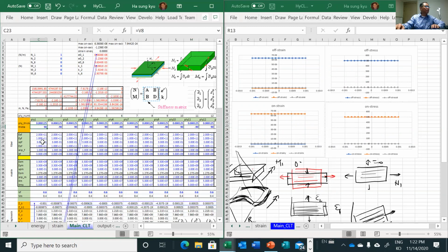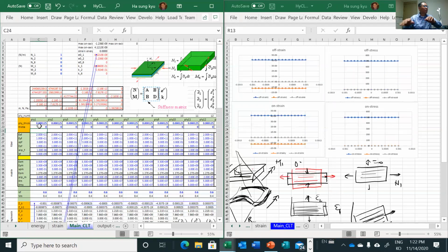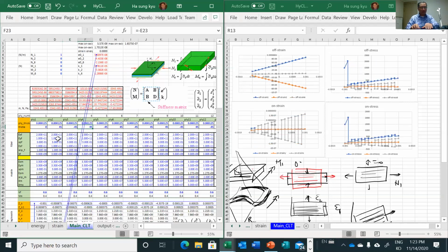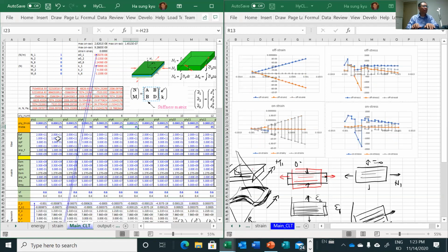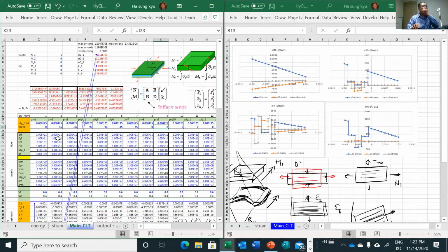Currently, the layup sequence is all 0. I would like to start with all 0, for the given uniaxial load, right? And then you can play with, say, what do you want to do? Say 45 and minus 45, and all kinds of angles can be specified. Any angle.